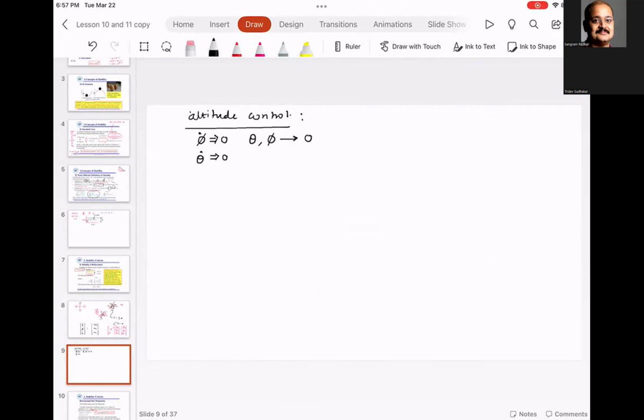So for Mambo, and I want you to try this, and I will explain it to you in just a few minutes using the code. Last time we had this sensor block. From the sensor block, what we did is we got the acceleration data, and this is the block diagram. From acceleration data, we got an angle, so this is where we are getting, maybe, theta. Then what we did, we got the gyro block.